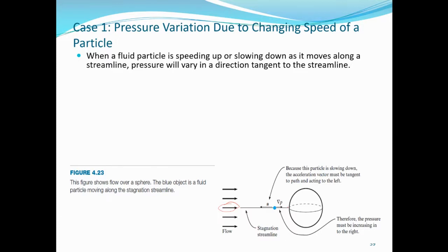You can have areas where you have no viscous effect or low viscous effect. But the stagnation streamline is the one that will hit the sphere at its center, and thereby coming to rest. The fluid particles along the stagnation streamline will come to rest after reaching the point where it will touch the sphere. That is this point.